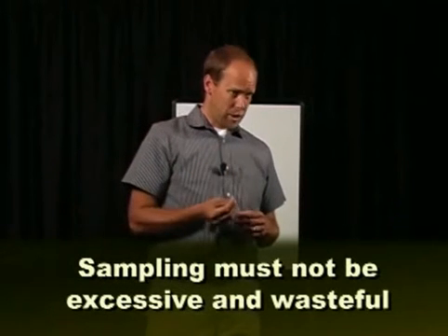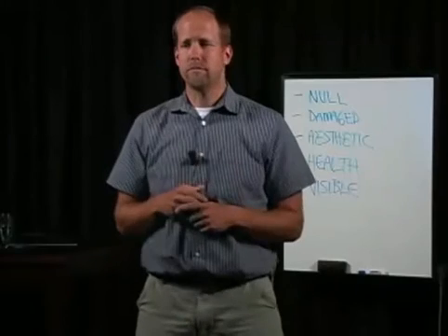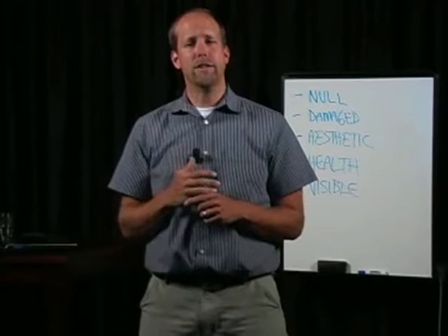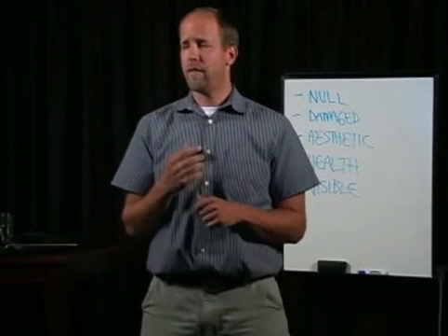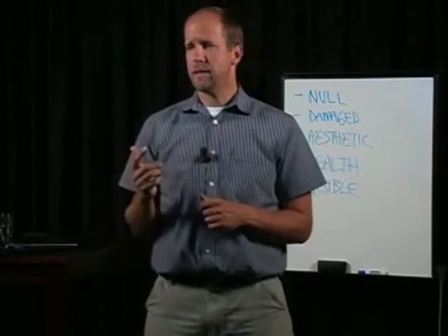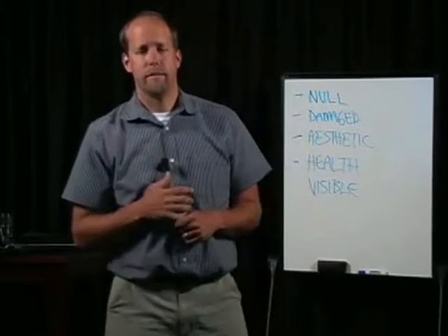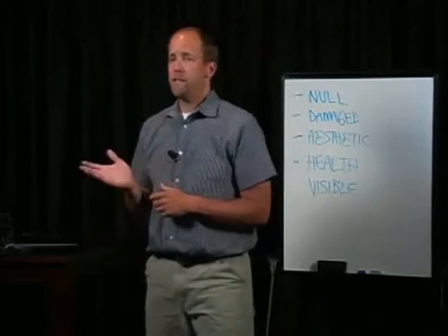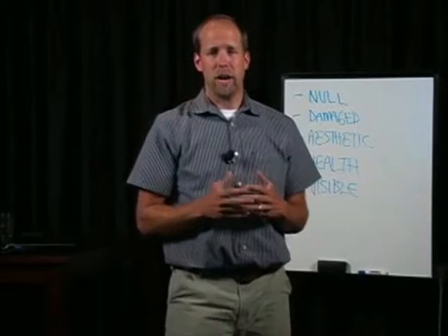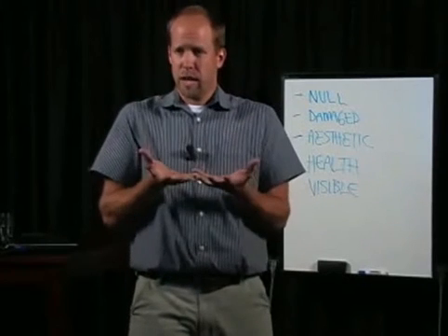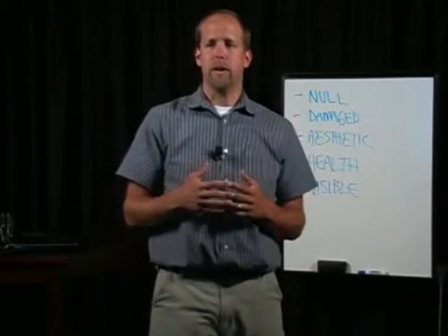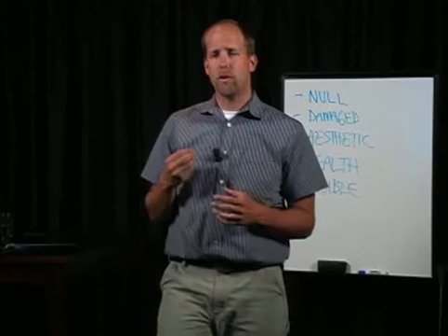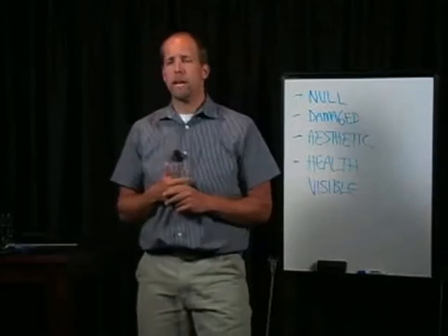Make recommendations. After finding apparent mold growth, the goal is to confirm that it is in fact mold. To report mold growth with care and accuracy is through sampling by a certified inspector and analysis by a certified laboratory. Sampling should be conducted if mold is inspected. After confirming mold growth at high or elevated concentration levels inside a building, then cleaning up and/or removal of the